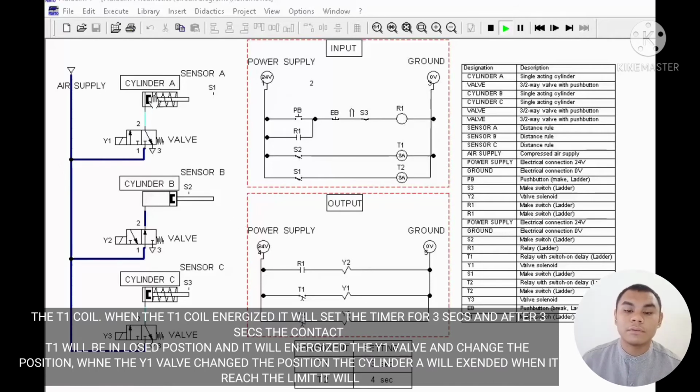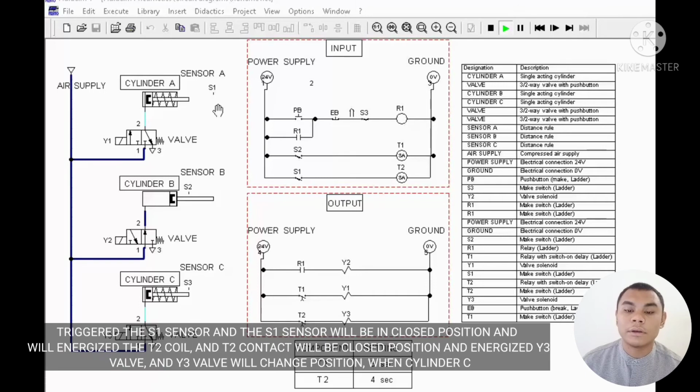When the Y1 valve changes position, cylinder A will extend, and when it reaches the limit, it will trigger the S1 sensor. The S1 sensor will be in the closed position and energize the T2 coil, an on-delay timer, and the T2 contact will be in the closed position and trigger the Y3 valve.